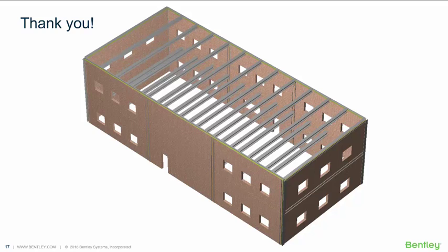How do you import from the RAM structural system to RAM Elements? When you're done in the RAM structural system, you close the model there, and then in RAM Elements, there's an option to import. And in the import category, there are two more options. One is the full model, and the other one is just the lateral model.